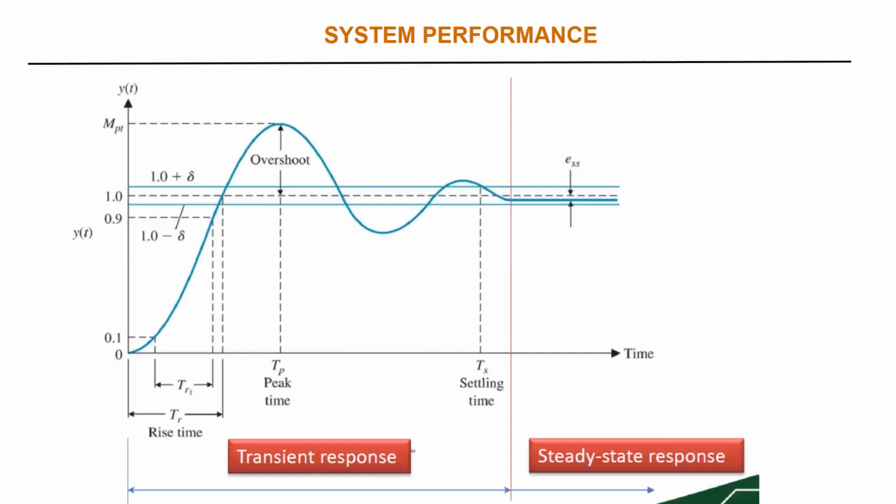So this is, as I said, the typical response of a second order system. My input is a step of 1. When you switch on your system, the system will overshoot first and then oscillate, and ultimately it will go to steady state. Now, from real life, what's an example of overshoot? DC motor. DC motor, okay. Where will the overshoot come? At first, it will not reach the maximum speed smoothly, then it will reach stability after some time. Exactly.